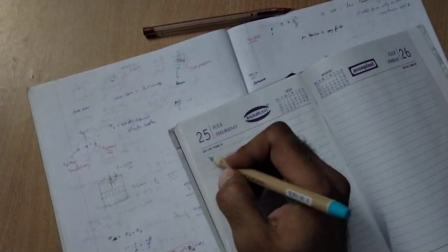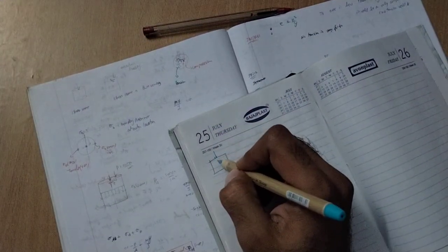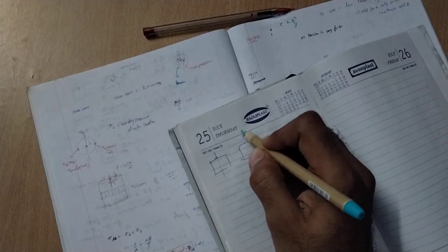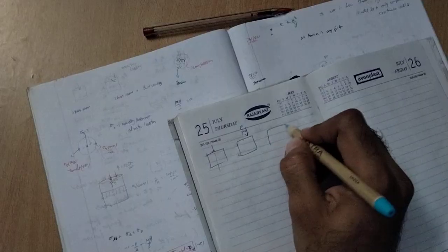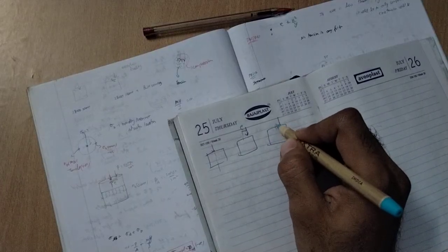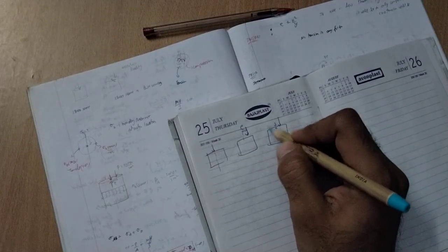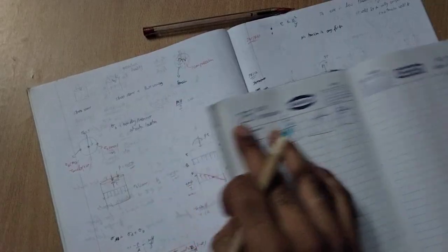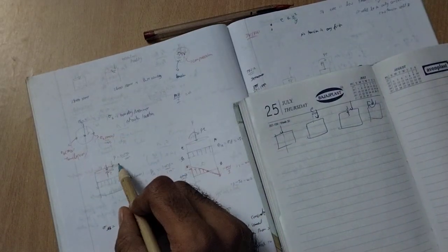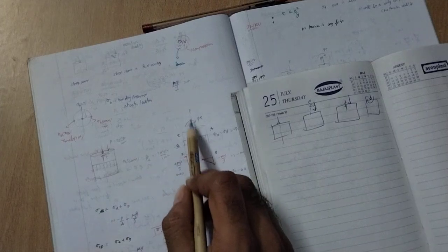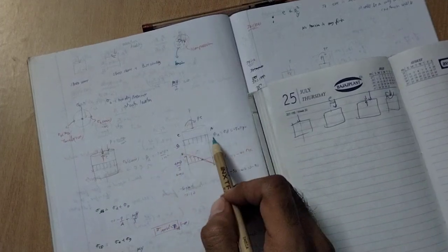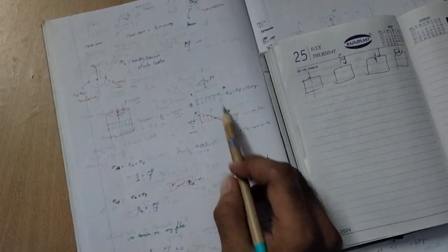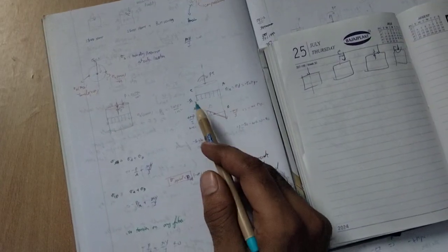So the other formula is, whenever the stress is given here it goes like this, but whenever the stress is given here you can see the eccentricity is there. So what will happen? This will just rotate. It means like this and like this. So two types of load are occurring, so here bending also will be. You can see P e and the stress. This one P will be the direct stress as well as the bending stress M y by I. So here everything will be plus, but here it will be minus.